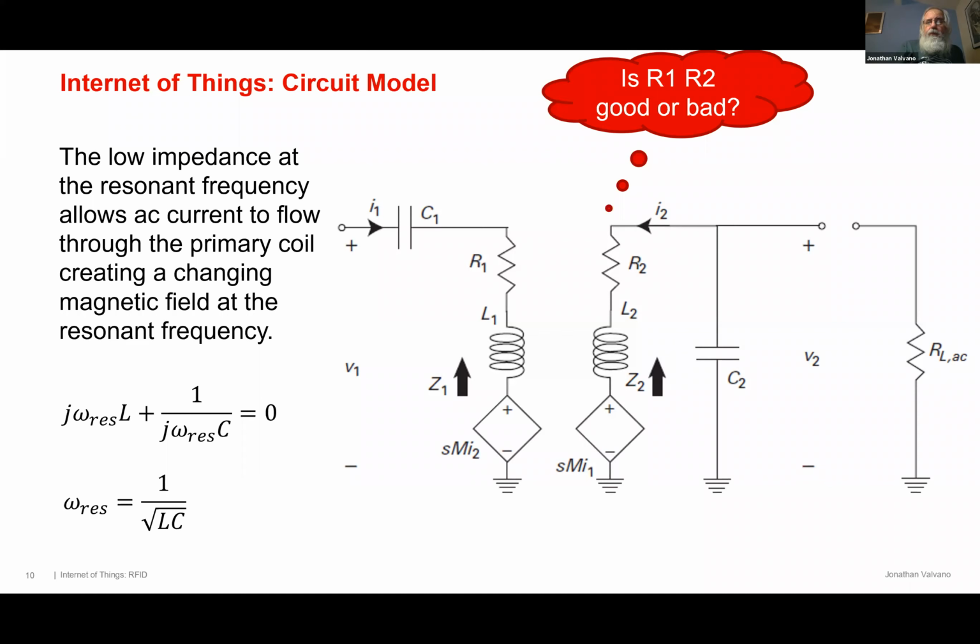And so if I just gave you a black box and said, I give you a constant V, how do you maximize I? What would be your approach? Lower the resistance. Not just R1, okay? You don't want to just lower R1. What do you want to lower? Assuming, okay, in here you see Z1 is the impedance of C1, R1, and L1. Z1 is the total impedance of this circuit, including 1 over j omega C plus R plus j omega L, right?